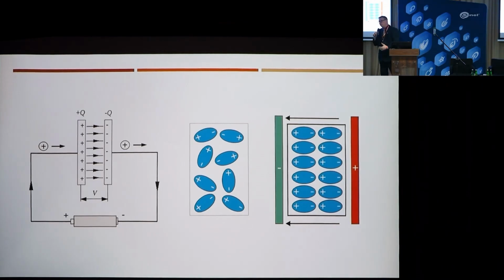And after those 3.5 hours, when the object's self-discharge process should also have taken place, it turned out there was still over 400 volts at the terminals. So ladies and gentlemen, you need to be careful with that. No rushing, no rushing.